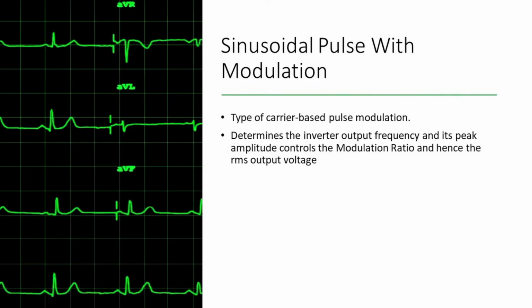When the sinusoidal wave has a higher magnitude, the output is high, otherwise it is low. The comparator output is processed in a trigger pulse generator in such a way that the output voltage wave has a pulse width in agreement with the comparator pulse width.